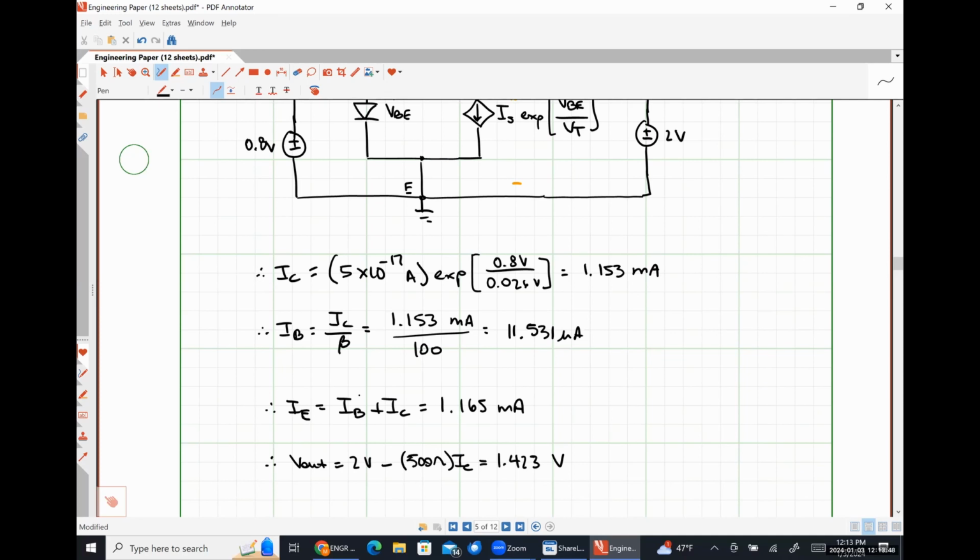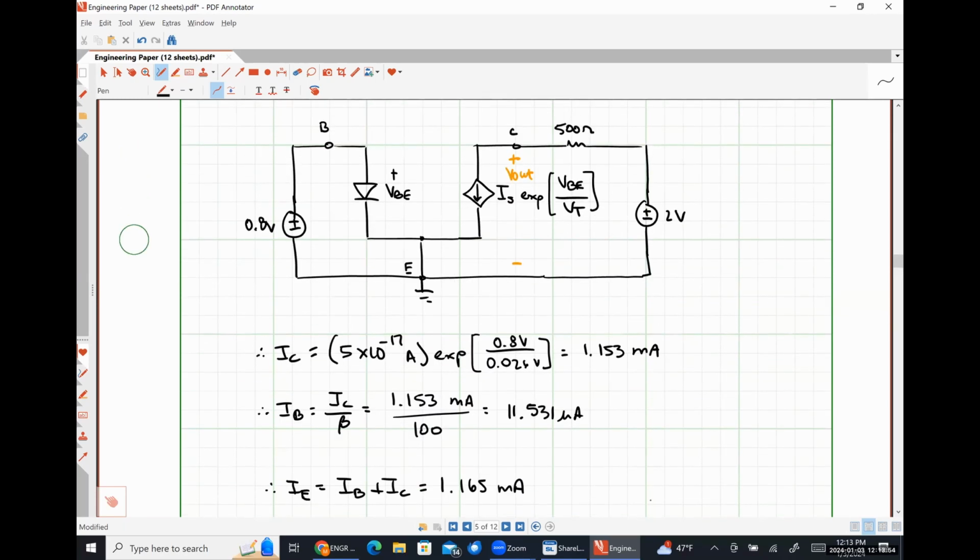What if we wanted to figure out what size resistor would put us at the edge of saturation region? Meaning, what's the limit on the resistor that we can choose here before we accidentally push this guy into saturation? This is a practical problem that we might face because we're trying to design the bias network for an amplifier, and we don't want to accidentally push it into saturation because it amplifies less efficiently in that region. Because we're 1 minute away from the end of class, we'll pick this up at the beginning of our next class, but this is what I want you to be thinking about before we go into our next class.